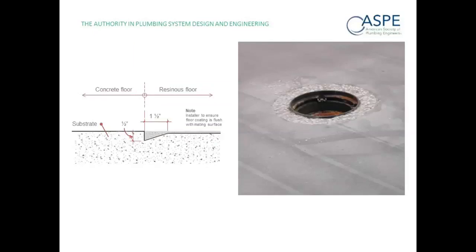And the same thing is true when you're trying to do your details for the floor. We want to make sure that we're keying everything into the drain or termination point. It's really the weakest part of any system is where it's terminating. So keying everything in is really critical, as you can see here in this detail.